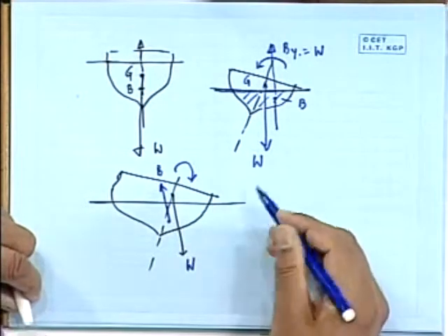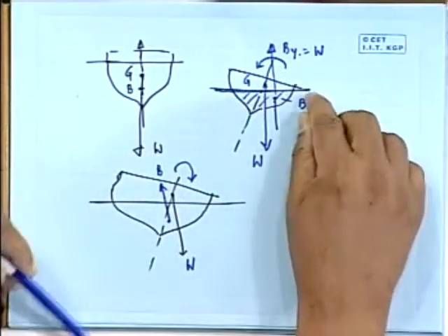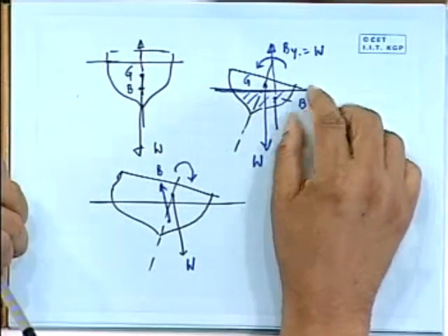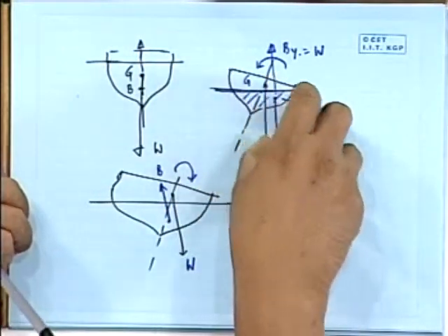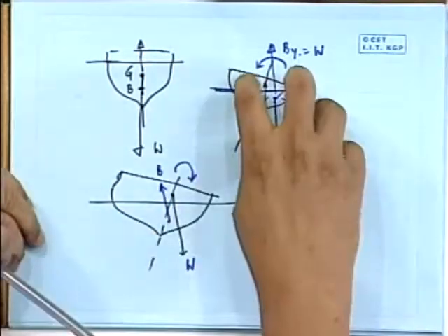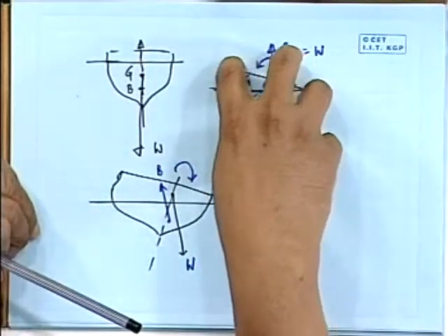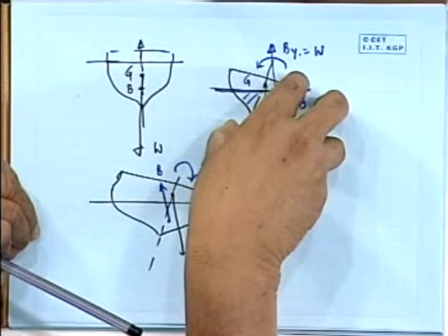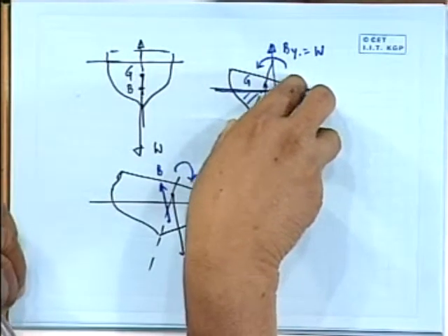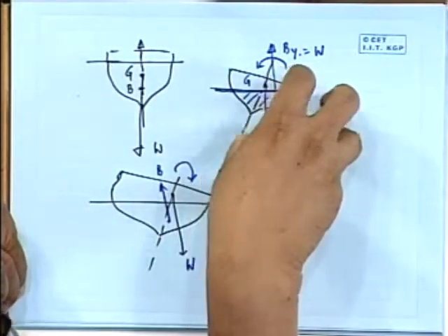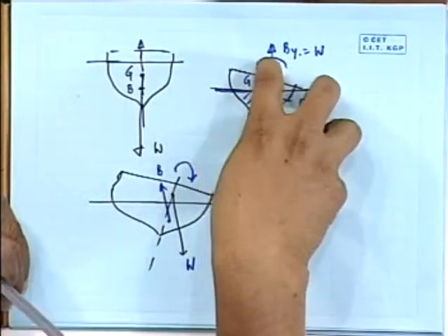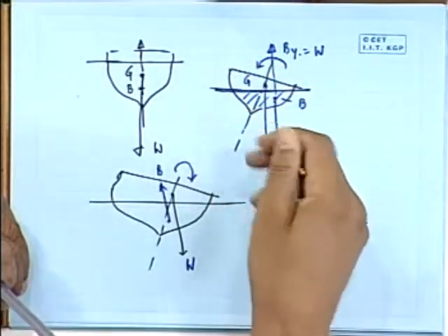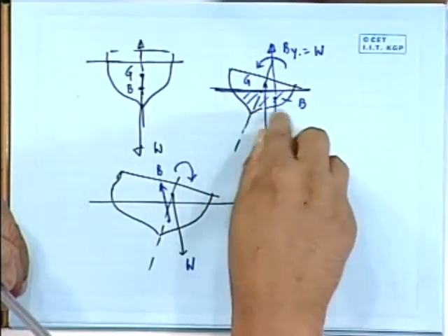And obviously what would happen is that it will try to actually increase the disturbance from equilibrium. So this becomes a case where the ship, when disturbed and the disturbance removed, see this angle was an external disturbance. Somebody has caused a wind or some wave would have caused it to tilt to some angle. That's an external influence. Then you have left that disturbance. The question that we want to examine is, should it come back to its original? All right. So here we see that in this scenario it is coming back.